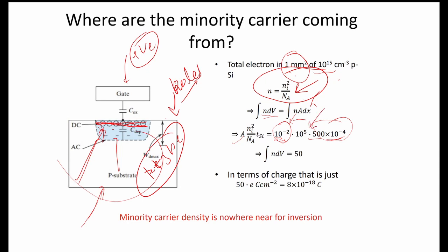And this is the electron concentration n p, Ni square by Na, 10 raised to power 5. So it comes to around 50. A 1 mm square piece of semiconductor has how many holes? Only 50. Okay, but as we are applying bias, this is not sufficient, but we are creating the electrons at this junction with the concentration of 10 raised to power 15 per centimeter cube.